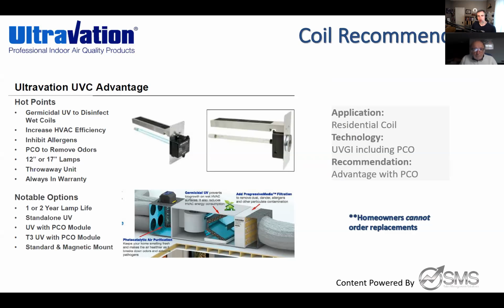And again, these are more often applied at the coil. Sometimes people add 2 or 3 of these. If they didn't buy a higher end system, they'll just buy a couple of these, maybe put one in the airstream as well with a carbon module add-on. But again, the best application for this is right over the coil. I can still add on a carbon module above that, and get some of that PCO we talked about, that photocatalytic oxidation. This will help with odors and other airborne particulates as well. We can get this in a regular non-T3 version or a T3 version, so you can get a 1-year life or a 2-year life option. This is something that Meyer Supply started with from the beginning. So again, entry level, simple, effective, it works.